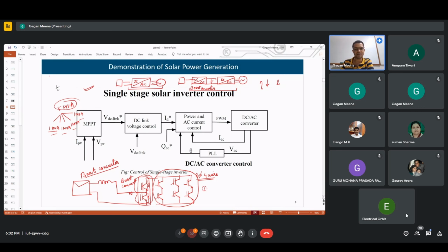And then in DC coupled, they are connected to a common DC bus, and an interlinking converter is used to link the DC and AC buses. And then in AC-DC, they are connected to DC and AC buses, and the buses are linked by these converters. Sorry, this is the interfacing converter, not interlinking. This is the interfacing converter, and this is the interlinking converter. So yes, ABC is correct.